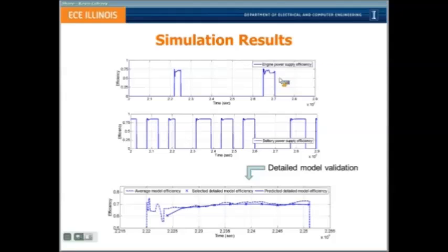Because when you presented your model, you said you're using a steady state model for the inductor here. You showed us a battery model with seconds, minutes, and hours. When we do transient stability simulation, for those of you who've taken 576, you start out with very detailed models, and then you say we can ignore the stator transients because they're fast. But on a 2 microsecond time scale, stator transients are still there. Did you include stator transients in your generator model?